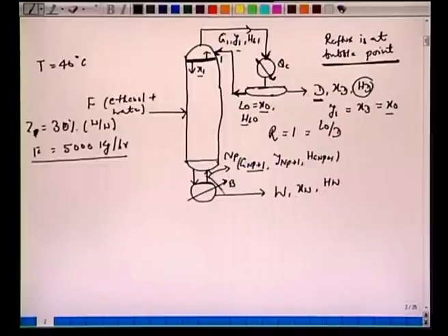So this vapor and liquid, they are in equilibrium, just like this vapor and the liquid, they are in equilibrium. Not this vapor with this liquid, although this condensation takes place at some condensation temperature Tc here. Similarly, there is a T1 here. At this T1, this vapor is in equilibrium with this liquid which is leaving, not with this liquid which is at this temperature Tc. Okay.